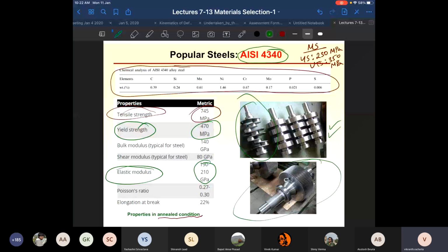So what do you think will be the nature of area of contact? It would be very low. The contact size will be very small. But on the other hand, what will be the kind of forces which will be transferred? If you are talking about a gear system, you would be transferring quite large forces but across very small areas. So what will happen to the contact stresses? The contact stresses will be very, very large.